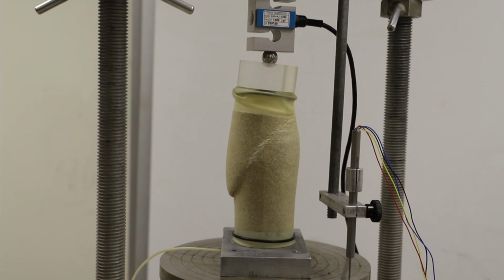So we're well past failure now, and of course at this point the additional deformations don't really tell us what the strain is very well, because we can't normalize it by the height of the specimen anymore. Somehow we should normalize it perhaps by the width of that zone, but that's pretty complicated, so we don't usually do that. We just recognize that once we see this localization, we're at failure. We can track the loads as they drop down, often to some residual value, and hopefully we'll see that in your data file as well.